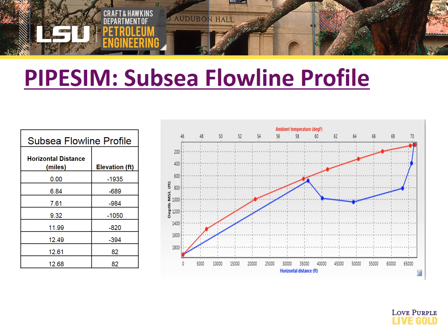For near or completely vertical pipes, Hagedorn and Brown is the most accurate method, whereas for most other cases, Beggs and Brill is an accepted method. The threshold you use for this angle to switch from one method to the other is somewhat subjective, but using 70 to 80 degrees is a safe assumption for the angle threshold. Our base case model is now complete. Next, Nick will go over our graphs to explain the results we obtain from running our simulations in PipeSim.